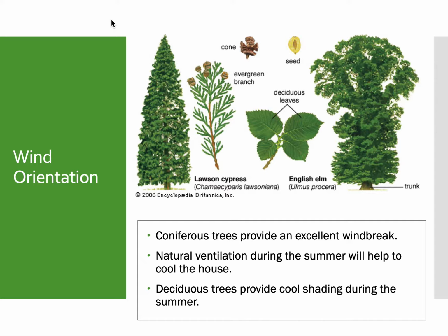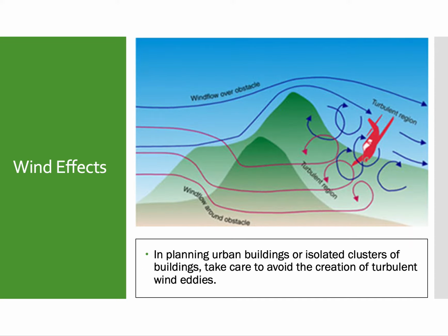So a tree that is planted on the face that gets southern exposure, the face that points north, in the summer could block the sun if it's a big tree like the elm or the oak. And then when it drops its leaves in the winter, now it's no longer an impediment to the sun getting into the house and warming it up. So trees, very, very great way to not only make the site beautiful, but to provide sustainable effects.